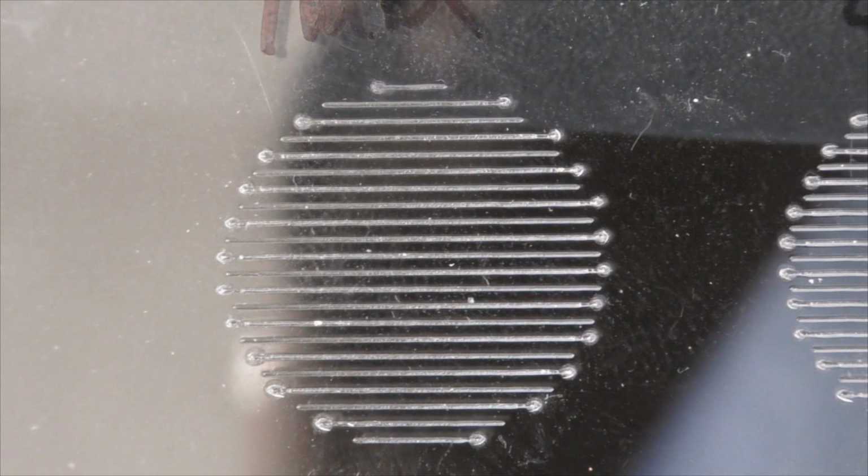Now, in looking at these results, two things I want you to remember. First of all, my dot size is around about 0.2 of a millimeter, i.e. that's the thickness of those lines, 0.2 of a millimeter. The second thing is that the picture that this was developed from was a pure black picture, which basically meant that as the scan started on the left hand side, it went to full power and continued all the way through to the other side and then stopped. So we'll quickly run through the results.